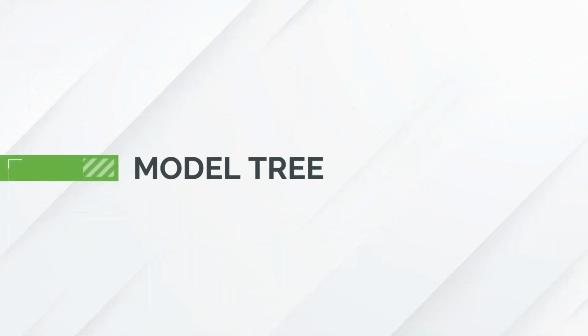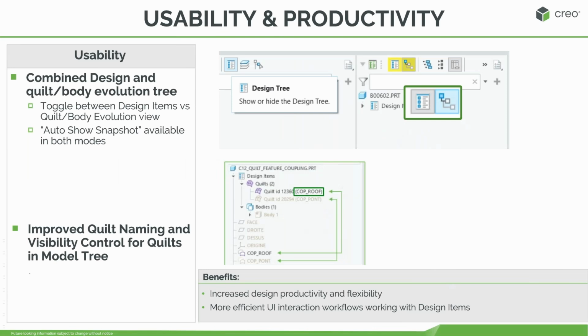Now let us focus on the model tree. With the introduction of multi-body parts, Creo also gave us two handy tools in the model tree, the design tree and the quilt evolution tree. The design tree shows you the features that make up the body or a quilt, and the evolution tree lets you see how that body or quilt has changed over time. Both are useful features, especially when working with complex body structures.